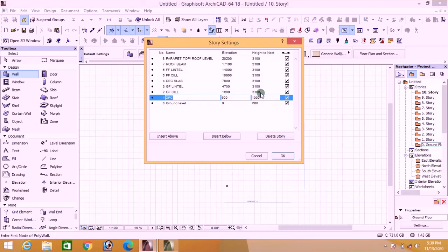Now, since we have laid 4 courses of block on top of DPC to get to seal level, what will be left is 5 courses of block, because we are laying 9 courses of block to attain lintel level. So 5 courses of block will consume 1250. So on top of our seal, we put 1250 to get to our lintel level. Now that we have arrived at lintel level, we are going to cast a lintel of 250. Then we'll lay 2 courses of block on top of it before we start marking our decking. Now, lintel of 250 plus 2 courses of block will give you 750.